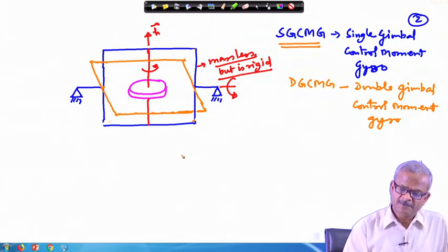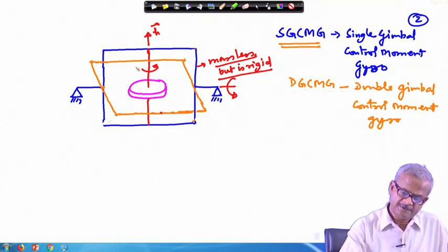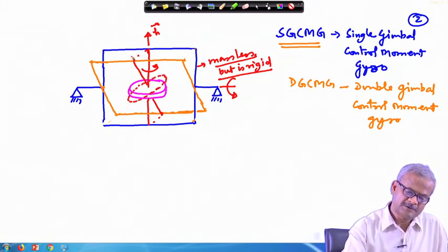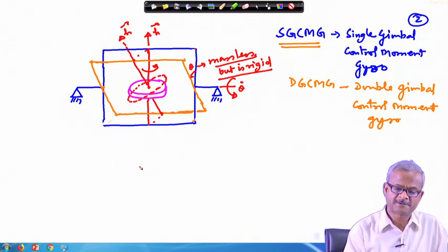As soon as we are rotating, this will also tilt. It is a rotation vector, it will tilt from this place to this place, and the rotation axis will come to this place, and then your disc will be oriented like this, meaning the h vector is now tilted. So, this is now the h vector, and assuming that the wheel is rotating at a constant speed, this angle we can show as the theta angle. So, theta dot will be present here in this case.